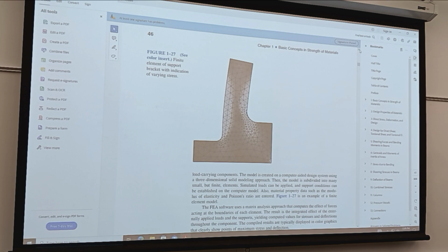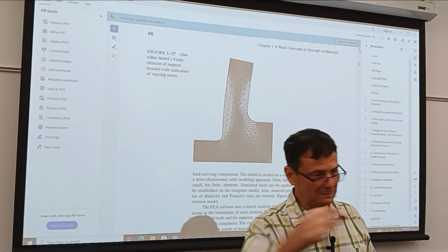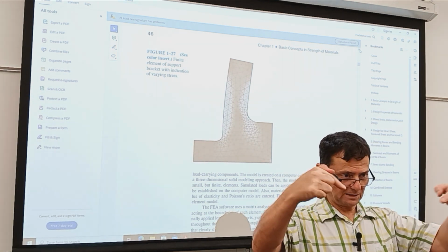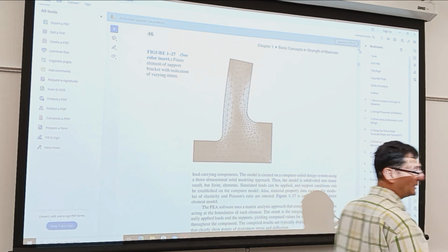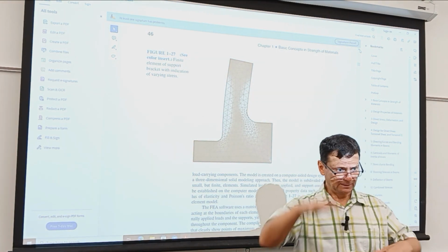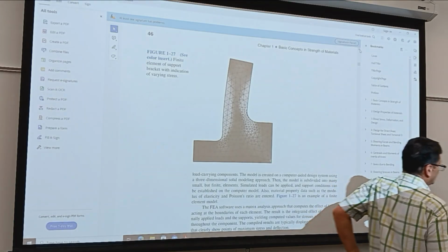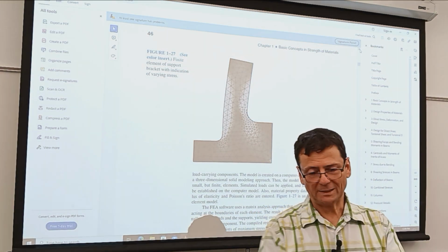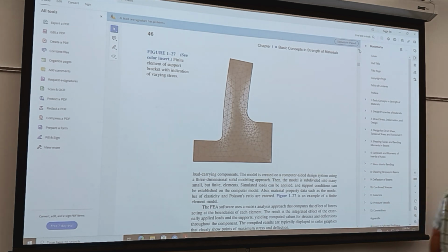I was looking for an example, we couldn't find it, but I knew of a study where the piston pin of engines, currently just a cylinder, got some more generous tapers at the end. The piston pin you want to be lighter weight because it moves with the piston, right? And the lighter the entire moving masses, the better for balancing or shaking reasons.